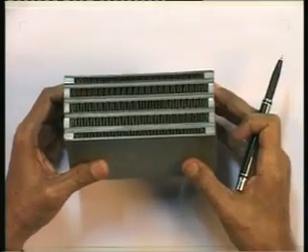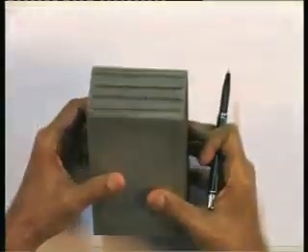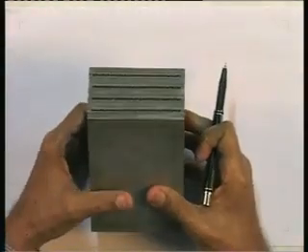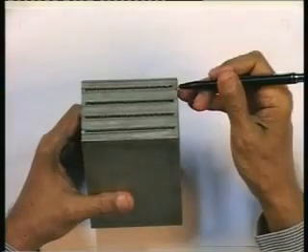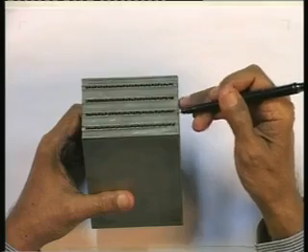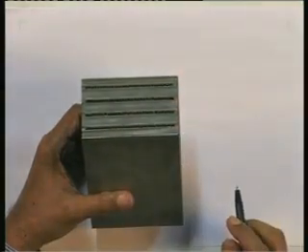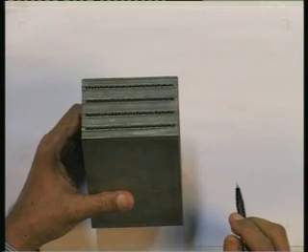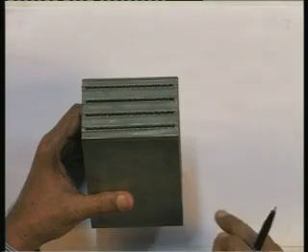This is one side, and then if I go to the other side, here we have the other side of the heat exchanger, where you can see I have the other fluid flowing through these channels, which are slightly narrower in width, and again we have fins here. So, it is an extended surface heat exchanger, or to describe it in terms of its geometry, it is a plate heat exchanger with fins.